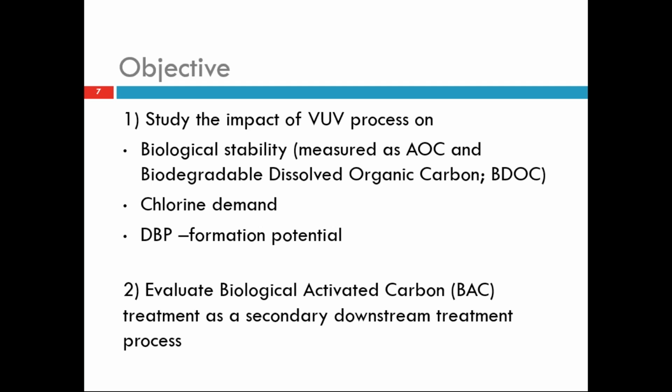Further, we also study impacts on DBP precursors, which are analyzed by chlorine demand and DBP formation potential. Further, we evaluate a biological activated carbon process downstream of vacuum UV, aiming at improvement in biological stability by reducing the AOC and BDOC in the water.